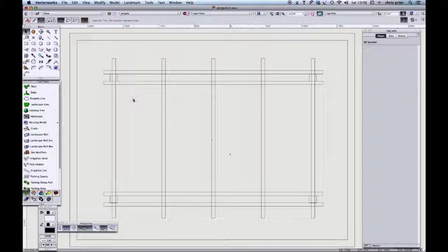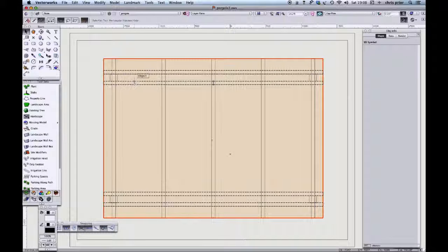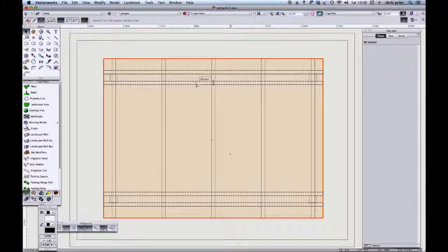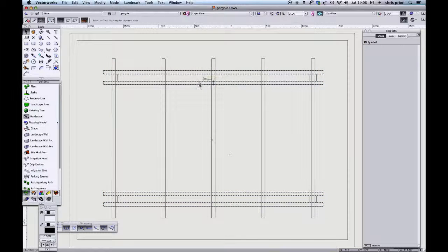That is because they're 3D objects and they haven't got any sort of characteristics which will make them look solid in 2D plan view. So the way that we get around that is we make it into a symbol, which is a hybrid object, which means that the object has a 2D component and a 3D component. So it has one particular sort of view when it's being used in 3D and another sort of view when it's being used in 2D.